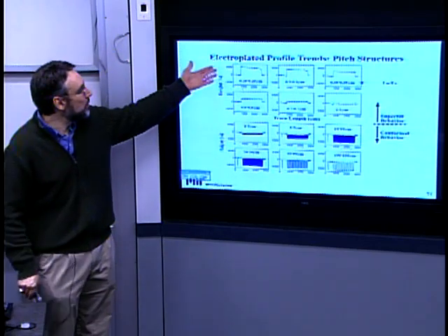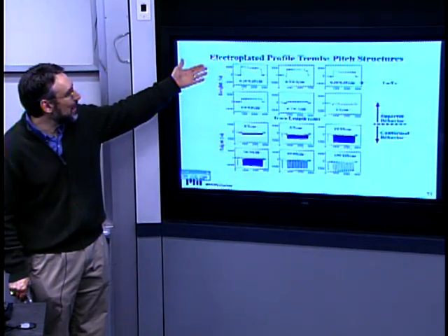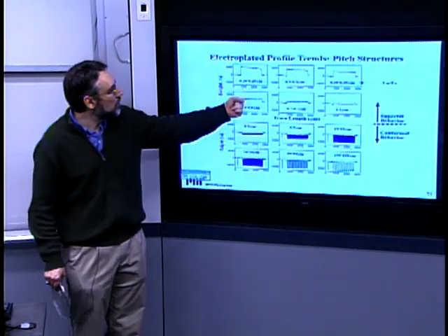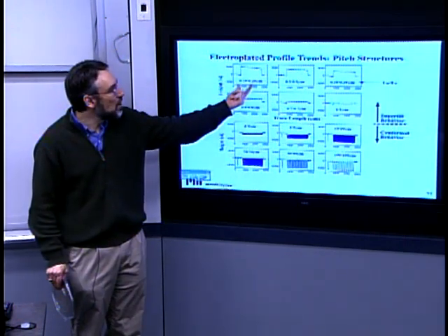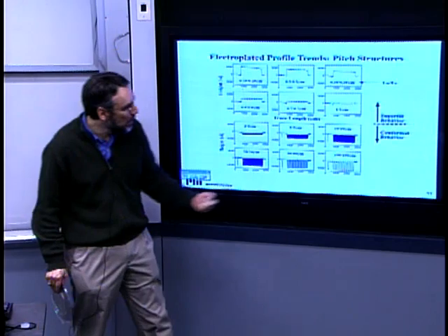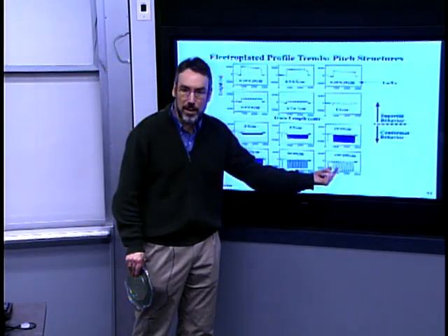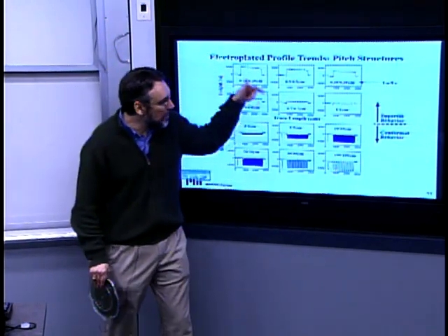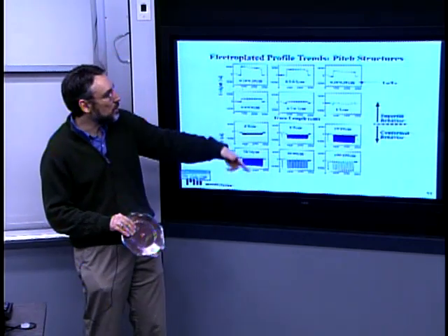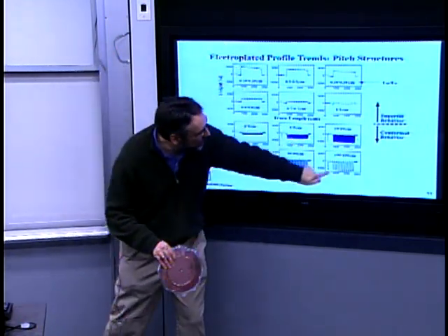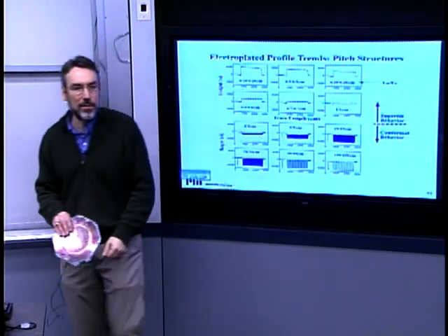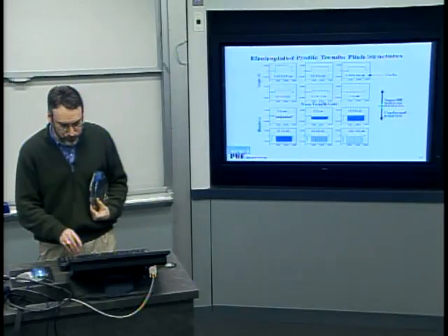So this is a measurement of the electroplated profile for different feature sizes, like those little lines and spaces between the lines of quarter micron versus, say, 100 micron and 100 micron lines. And then you could measure the surface topography and see how much overplating or how much underfill you might have in each of those regions.